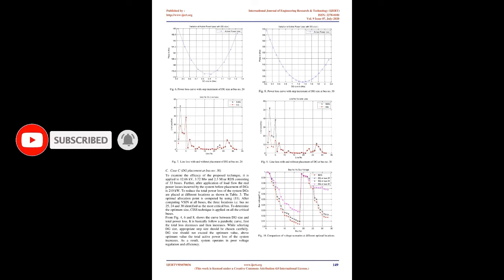For results and discussions, Fig 3 shows the single line diagram of the 33 bus radial distribution system. The detailed methodology of the proposed method is described by the flowchart shown in Fig 2. The proposed flowchart is described in 2 steps. At first, the optimal location of DGs is calculated using VSNI. The tabulated values of VSNI are shown in Table 1. Table 1 indicates the active and reactive power consumed by different buses and their corresponding VSNI values. In the next step, the optimal size of the DGs is determined using the continuous increment of step size, CISS, technique with a step size of 0.1 MW.